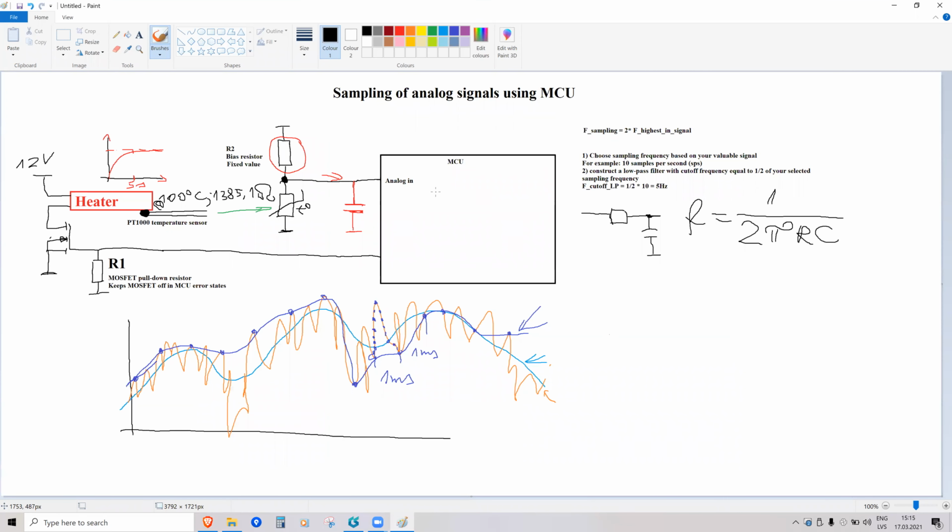1,385.1 ohms. The voltage reference inside the microcontroller will be, for example, a 1.1 volt voltage reference. So the analog signal should change from approximately 0 to 1.1 volts. Higher resistance will give higher volts, so we need to assume that at this resistance there will be 1.1 volts. And from this, we can calculate the top resistor.